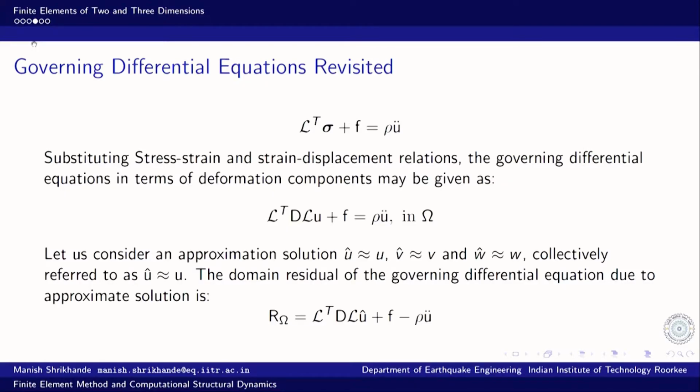And once we take into account the generalized Hooke's law to relate stresses to strains, and then the definition of the strain components relating strains to the deformation, we can transform the governing differential equation in terms of the deformations. That governing differential equation can be given in terms of a differential operator L that relates strains to displacement.